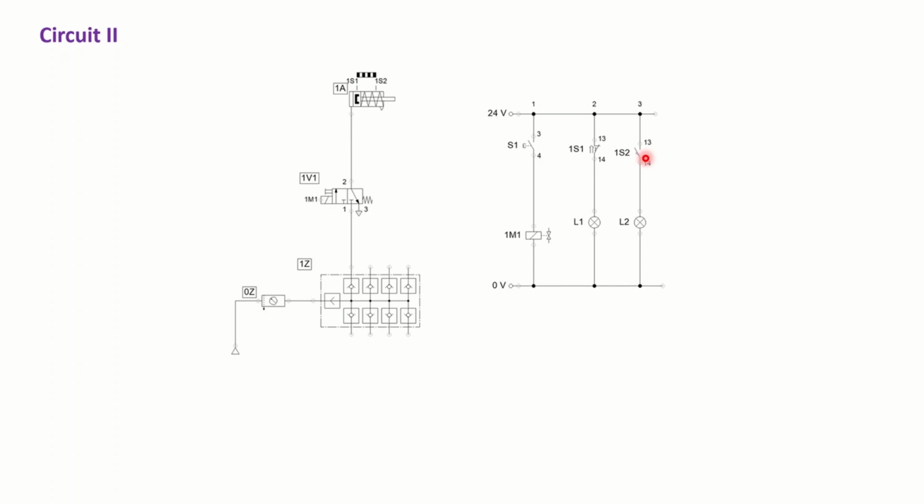And if you remember, when I was talking about the displacement step diagram and the sequences that we have in pneumatic based systems, you can watch our video on displacement step diagram and sequences. In those videos, we were using labeling and mechanical actuation. We had mechanical actuation for the directional control valves, and those valves were linked to the position of the piston inside a single or double acting cylinder.